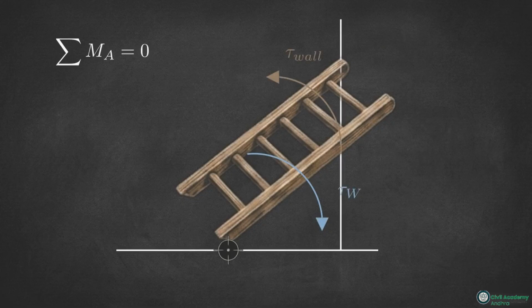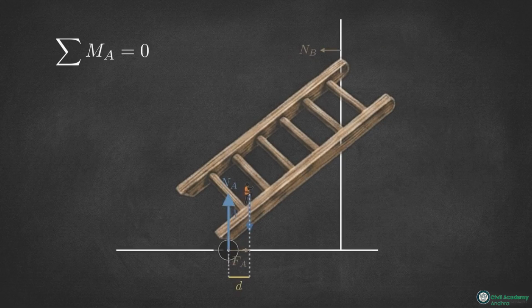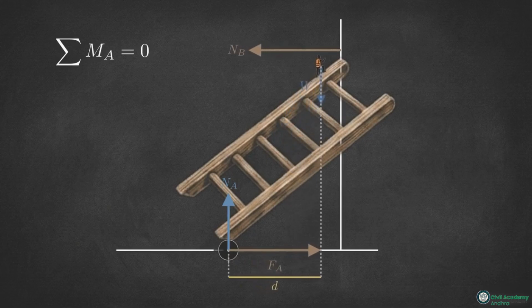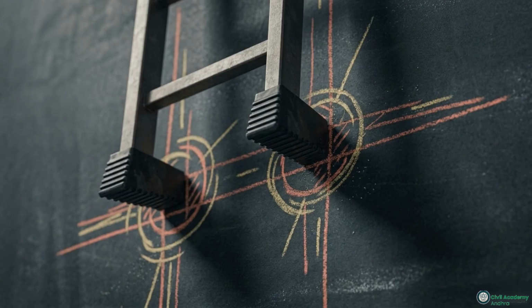As the climber moves up the ladder, their changing position shifts the rotational balance. This dynamically alters the normal forces at the contact points, pushing the system towards its frictional limits at the floor and wall simultaneously. For non-concurrent geometry, the threshold of failure is governed just as much by torque and rotational pivot points as it is by the raw friction vectors.